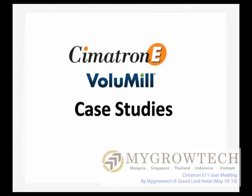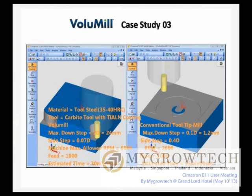I'm going to cut a 3D part. This is actually a punch for some stamping die, okay? And the material is some kind of tool steel, and 35 to 40 HRC, very hard material. Okay, and the tool is carbide tool with the black coating, yeah. And this is what I did. The diameter is 12 mm, 12 mm diameters, and I'm actually using 2D to rough the part for the VoluMill.